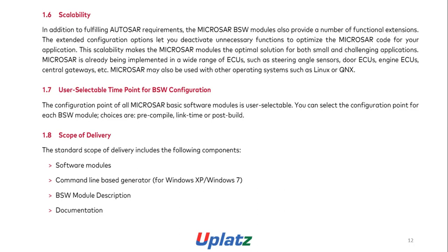User selectable time point for BSW configuration. The configuration point of all MICROSAR pieces is user selectable. You can select the configuration point for each BSW module. Choices are pre-compile, link time, or post-build.